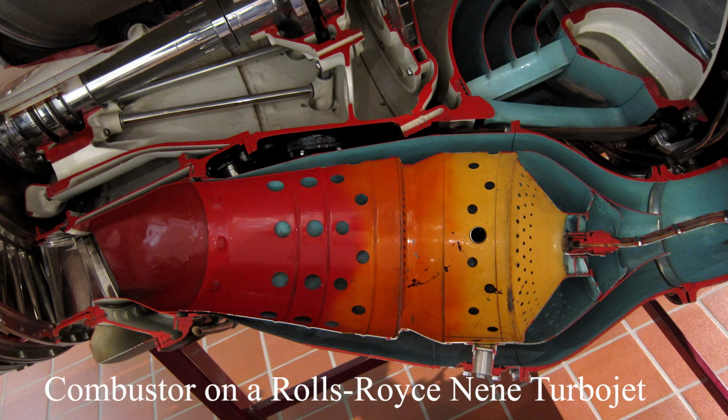Once smoke was essentially eliminated, efforts turned in the 1970s to reducing other emissions, like unburned hydrocarbons and carbon monoxide. The 1970s also saw improvement in combustor durability, as new manufacturing methods improved liner lifetime by nearly 100 times that of early liners. In the 1980s, combustors began to improve their efficiency across the whole operating range. Combustors tended to be highly efficient with 99% plus at full power, but that efficiency dropped off at lower settings. Development over that decade improved efficiencies at lower levels.